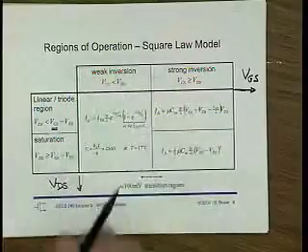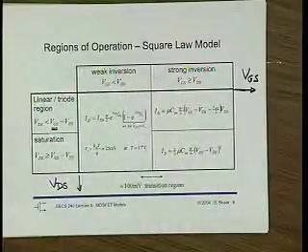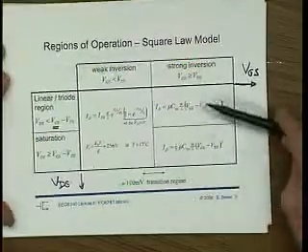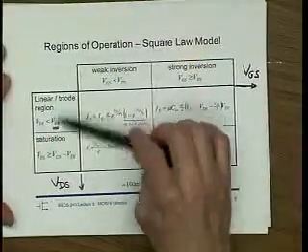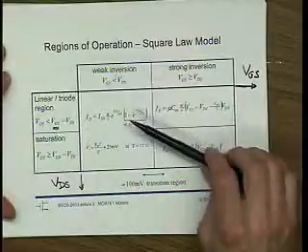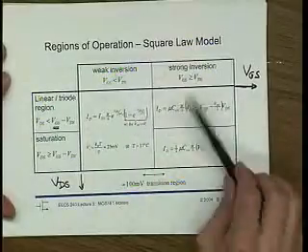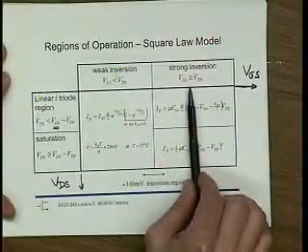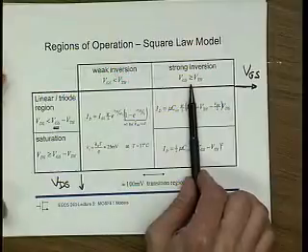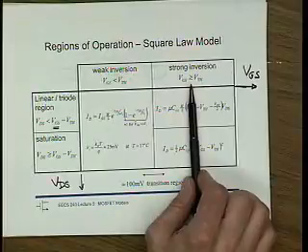So there is probably nothing new in this entire chart for you, with the exception that some may not have seen the equation for weak inversion. These two equations, I'm sure you have seen. Some simple descriptions of transistors say that if I make VGS smaller than the threshold voltage of the transistor, then the current immediately drops down to 0.